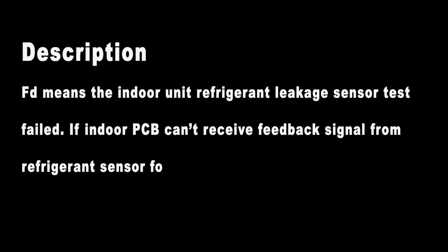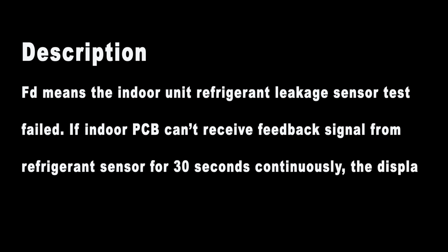FD means the indoor unit refrigerant leakage sensor test failed. If the indoor PCB can't receive a feedback signal from the refrigerant sensor for 30 seconds continuously, the display will show the FD failure code.